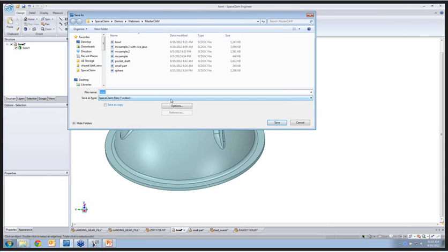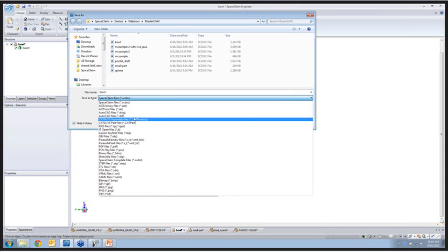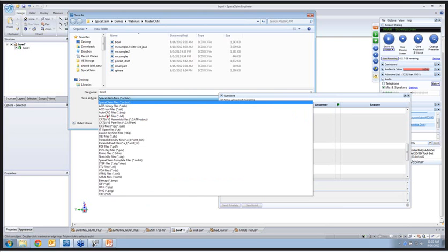Instead of saving to the native CAD systems, we'll save as the neutral file formats. The exception would be CATIA, but we save out to ACIS, AutoCAD, IGES, JT, Parasolid, STEP file. The reason is if I take NX Unigraphics, for example, the native kernel they run on is Parasolid. There's really no difference between if I were to give you a PRT file or an X_T or X_B. It's the same thing. The geometry is just the same. Either way, when we bring a model into SpaceClaim, we dump the history tree, so it's never there if we were to export it out.